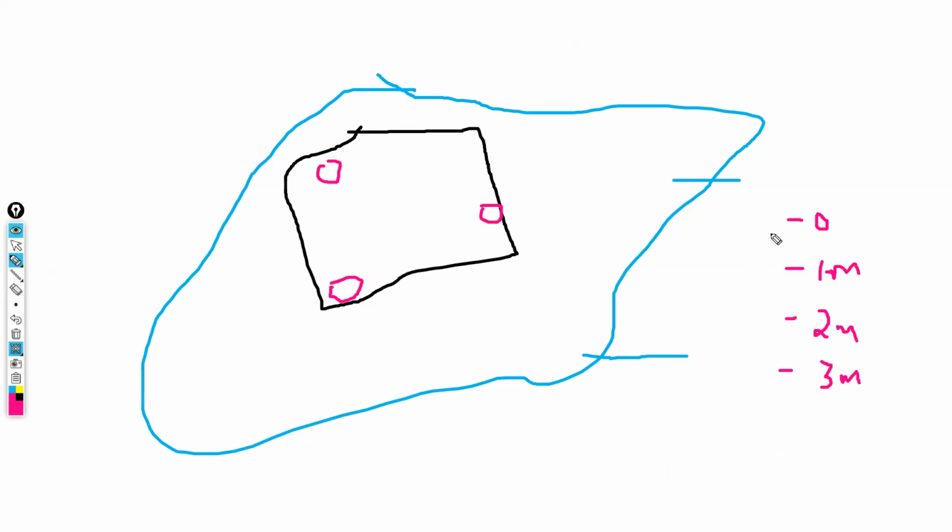So you might find that for this trial pit, when you are at 0, the bearing capacity of the soil is maybe 170. And then when you went to 1 meter, it became, let's say, 162.